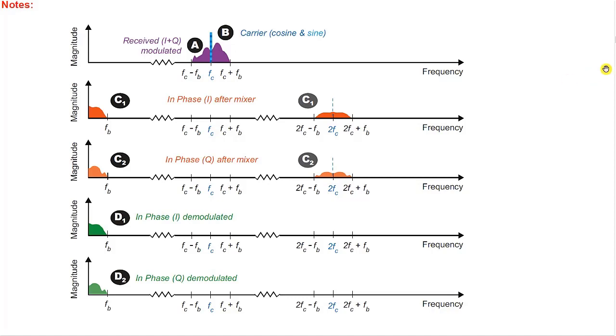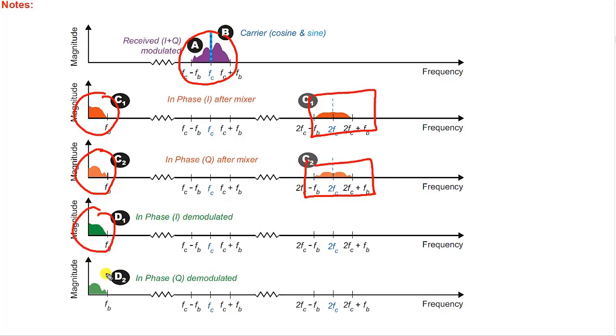So we can see here that if we receive the signal that we just transmitted a few seconds ago, then after we mix down to baseband in the cosine and in the sine channels, we get a couple of baseband signals. Of course, we get components at twice the carrier, and we filter these off and we get back to the baseband. Now, there's many aspects of synchronization, phase synchronization, frequency synchronization that we must do, and we will do in the RFSoC, but that's not something we have the time to present today. But clearly, synchronization is a core part of radio architectures.